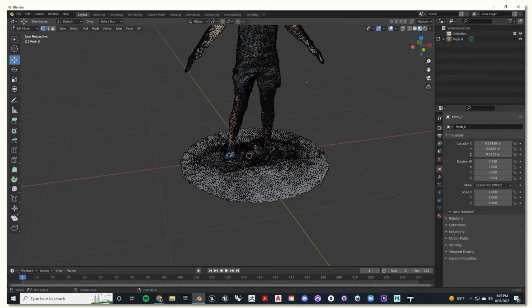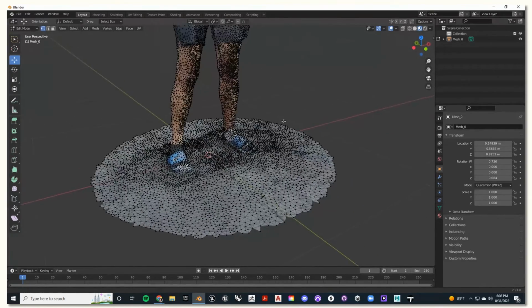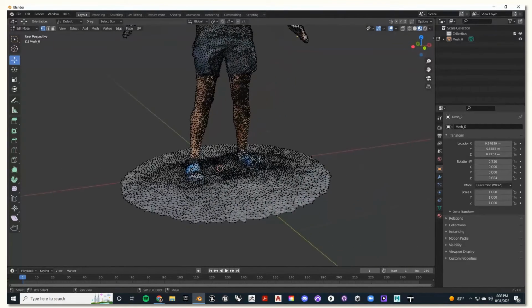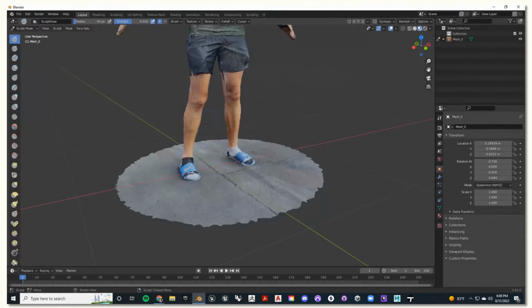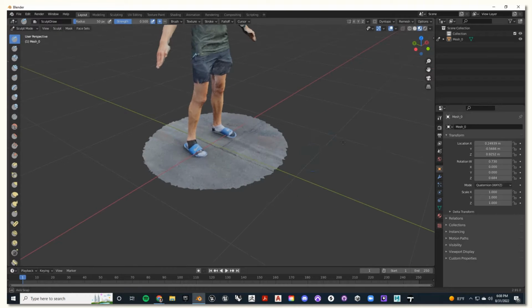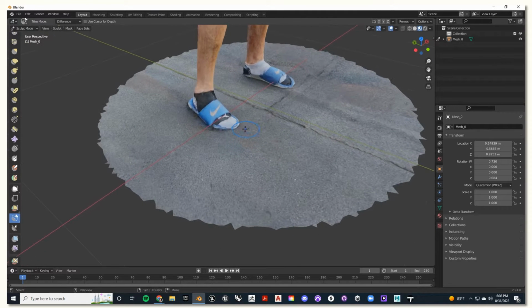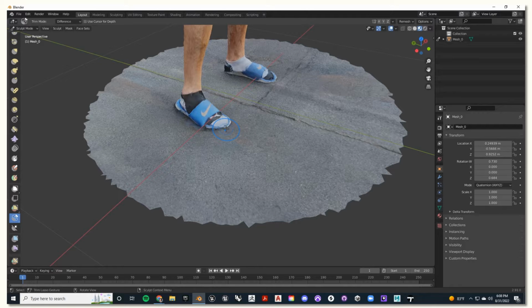Excellent. Now our next step is going to be cleaning up this bottom patch where his feet are touching the roof, and then making sure his feet are both in line. Go to Sculpt Mode in the top left-hand corner, and you'll find at the bottom left the Lasso Trim tool in the Sculpt bar. With this tool we can trim in an organic pattern that we like. Once you find a good patch, just drag and trim any unwanted mesh.